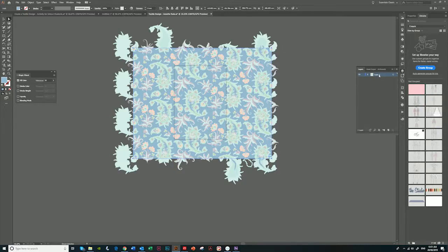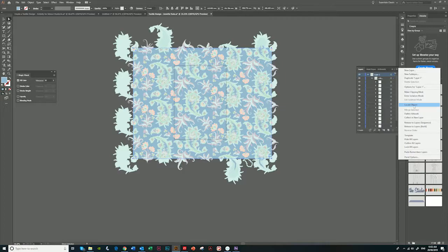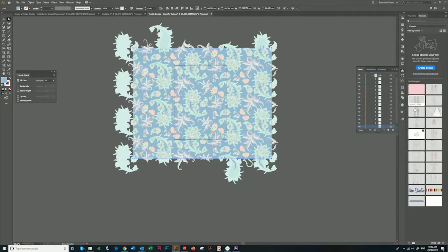Once we've got to the layers, rather than clicking on the drop down and going through your grouping, we just go over to our menu and locate object, because this one is the one that's selected. It will find that one. And as you can see, we scroll down a little bit more, you can see that's our color field, and then that's our boundary box. What we want to do is click, hold and drag and create a second one of your colour fill. This will give us a shape that we can now use to convert to an artboard.